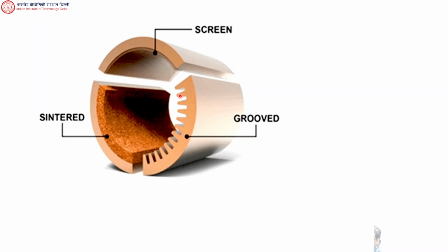In the condenser, it loses heat and the vapor becomes liquid, and the liquid then goes through the wick to move towards the evaporator. Then the same thing continues. So you don't have to keep adding water. If you have a heat pipe, it has the liquid and keeps doing all this and keeps transporting heat.